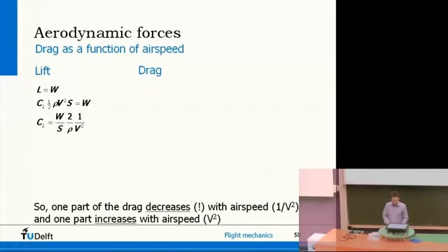But now let's have a look at the drag. We've just gotten this relationship, the aerodynamic lift-drag polar, which says there are two portions to the drag: there's this zero-lift drag coefficient, and there's this induced drag. Just to remind you, this term and pi and A and e are all constants for a given aircraft.